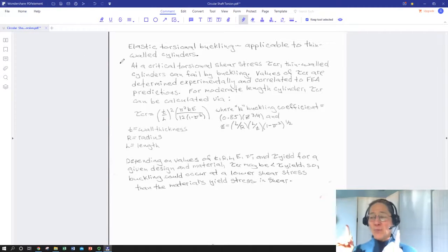Okay, we're going to pick up one last topic. This is something that we'll get again with column buckling in what will probably be the final section of your study of mechanics of materials, but this is a little look ahead towards it, because a column sometimes will be subject to twisting loads. And columns will buckle under compressive loads. Torsional shafts, if they are thin-walled cylinders, can also buckle when we twist them. If you get a thin aluminum can and twist it, you can see it doing that.